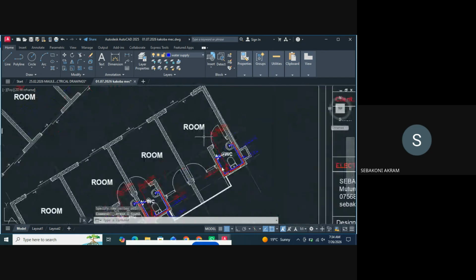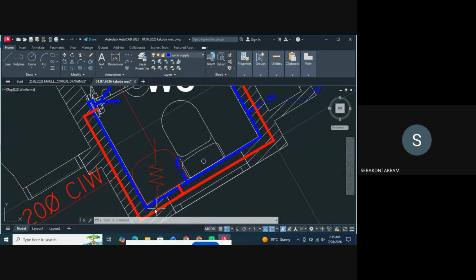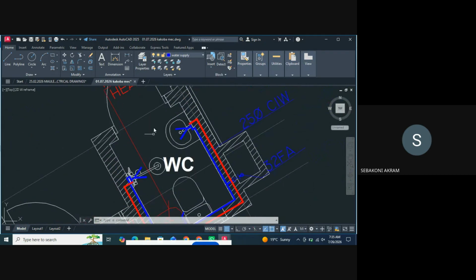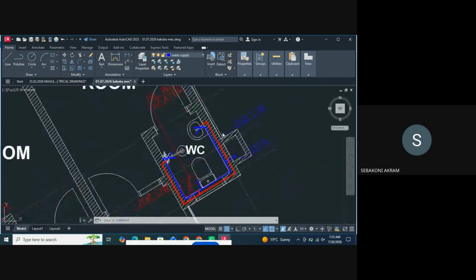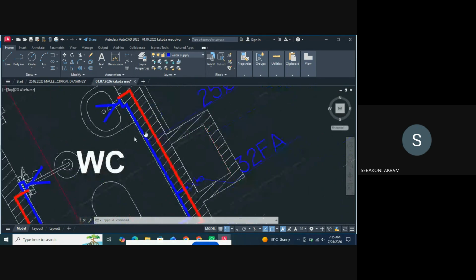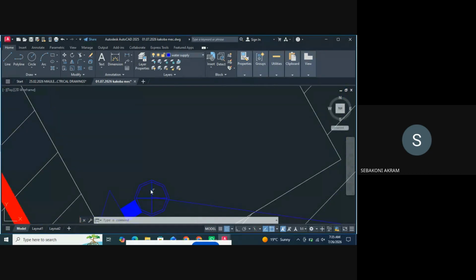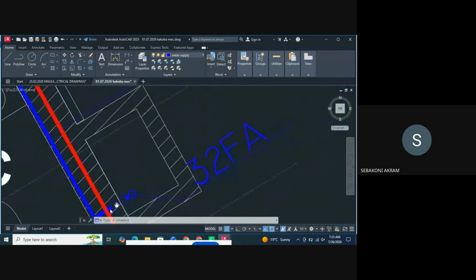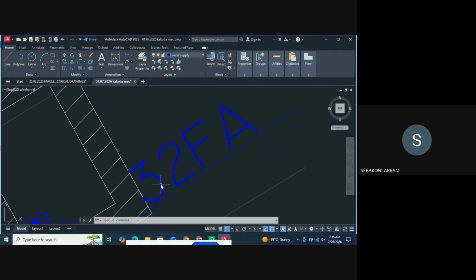So we've seen that. So that's how I came up with this. Have you seen it? So for water supply, these pipes are casted in the wall. And since the water is being driven by gravity, the most concern is this pipe that is supplying from the top of the tank. This one here. It's the one that you usually size. You getting me?